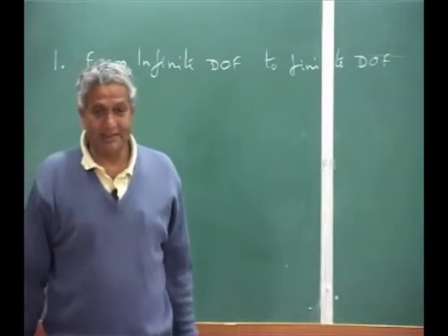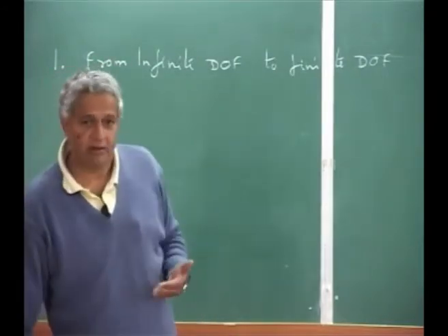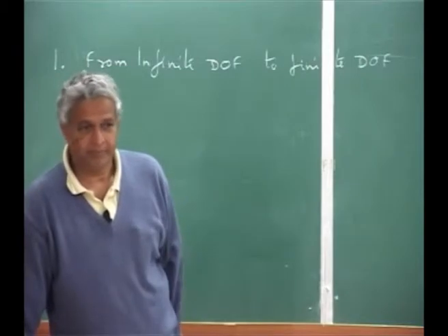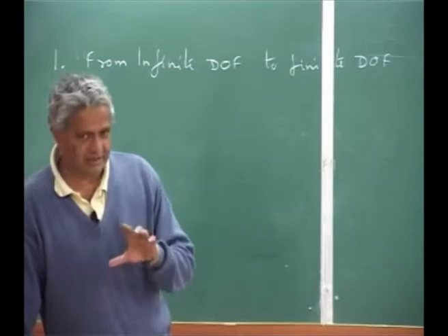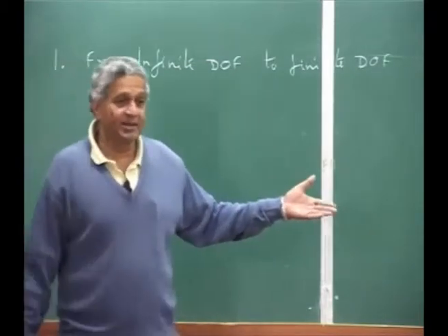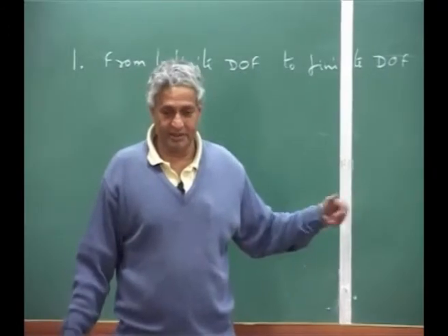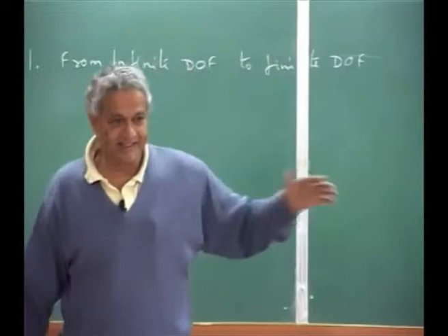You reduce it. Now the question arises, how many finite modes should you treat? That's why I said in the case of a rotor blade, we take about 8 modes. Okay, 3 in one side bending, 2 in the other bending, 1 torsion and axial, like that.